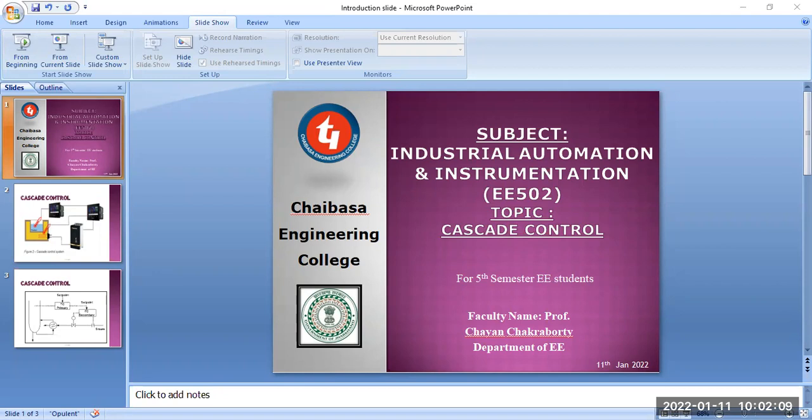In the second picture, this is primarily taken. This is our primary. We are taking the temperature of this, and then in the secondary case we are considering the heater, or it may be a heat exchanger. The heat exchanger is driven by your steam flow. So this is called a heat exchanger, and in this way we can control the secondary also. So this is our cascade control loop. I think you can get a glimpse of the idea regarding this cascade control system.